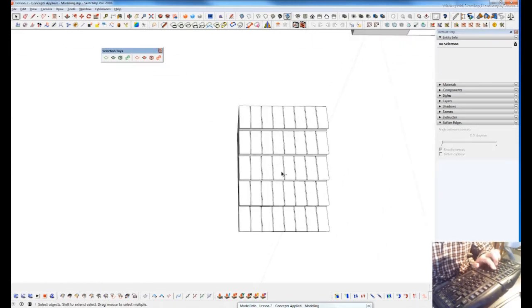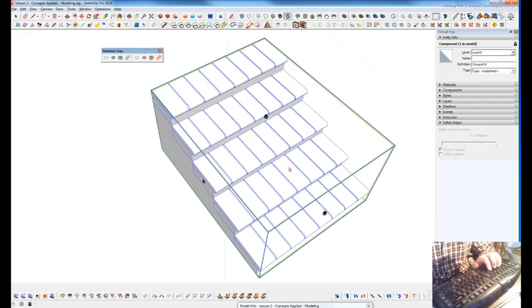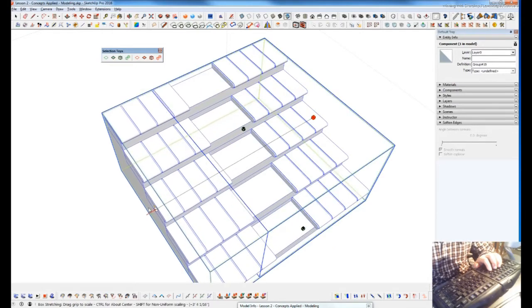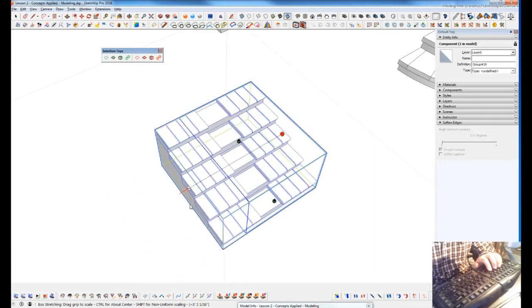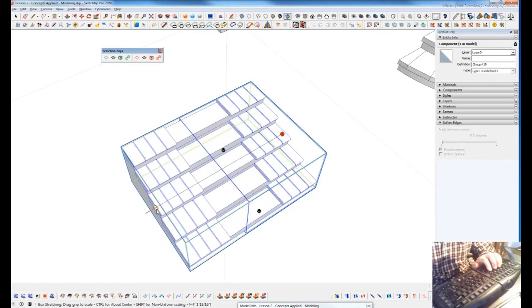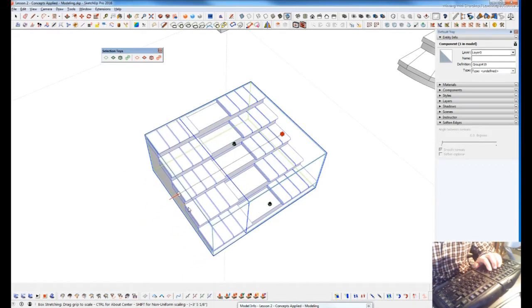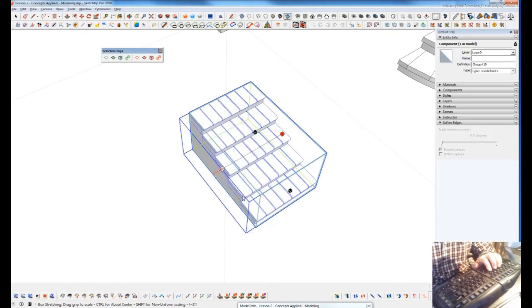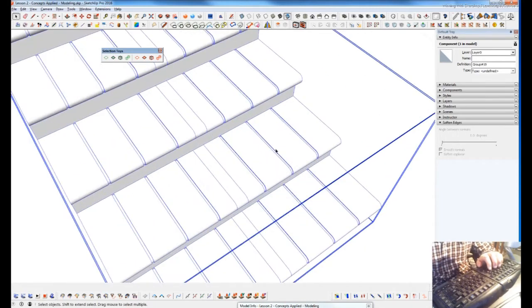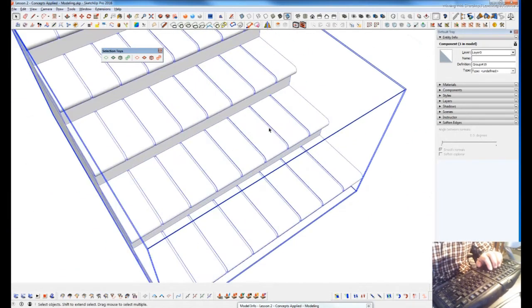When it comes to the box scaling, that Control-Shift-R, I select that and go to Control-Shift-R. Now, there's actually a plane in between, and watch what happens. As I scale this, it doesn't stretch out those bullnose. It's scaling at the base level component and then splitting those in half, which would allow me to now add extra in there without messing up the scale that we created when we created these, because they were built to scale.